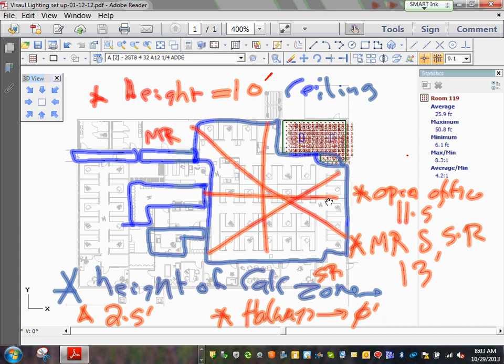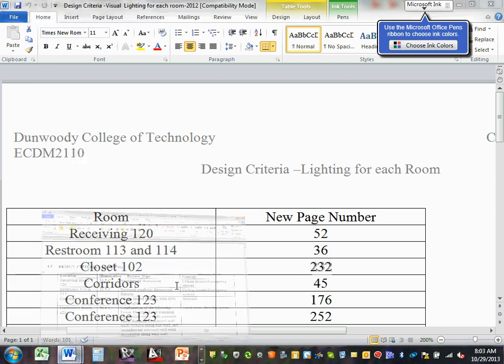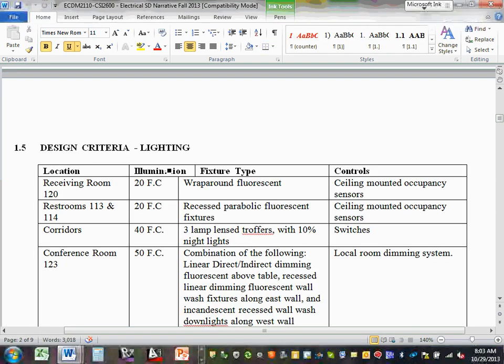Okay, now, what's the big fuss? Why are we doing all this? You're doing it, guys, for this. Do you see this value here? 25.9 foot candle. That's the value that we're given here by the engineering firms. This value corresponds to this value, right? Do you guys remember? Here's that 20. I have a 20-foot candle here, right? I need to go do my calculation so I can get 20-foot candle, or plus or minus 1 or 2.